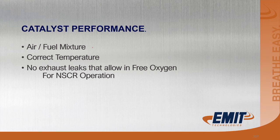Catalyst performance, there's a few things that you can do. When you and I are trying to adjust an engine or tune it or adjust it for emissions, some of the main things we have to look out for that we have control of are the air-fuel mixture, that's number one, the correct temperature. If the temperatures are too low or too high: too low, the catalyst won't perform the way it should. Too high, you'll damage the catalyst.